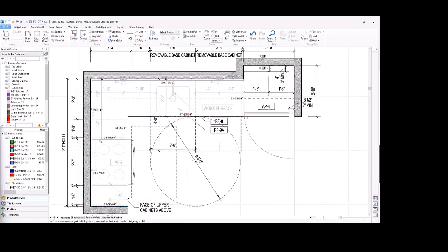Then I'll left click to drop that in. So we're not done yet. We still got to create an area for that stove to go. So what I'll do is I'll click on this red little diamond shaped handle for this seam, left click and just drag it down. Drag it down to make shape for that stove. And so that's how you make space for your objects such as your fridge or your stove here.